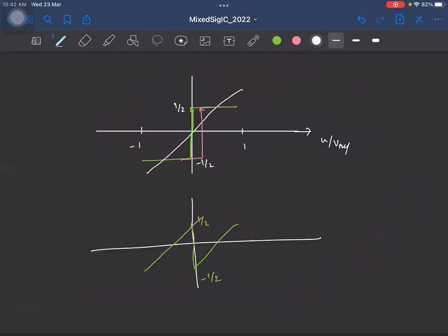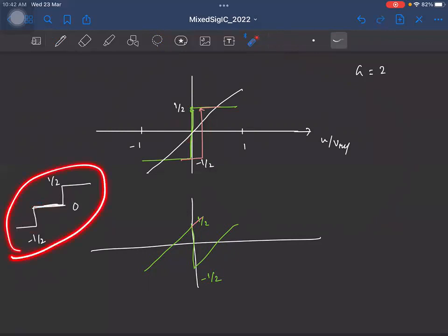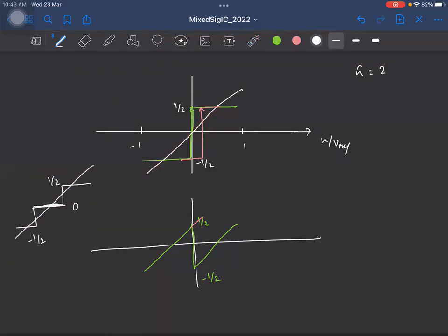So the point is, if I have a gain of 2, having a 2-level quantizer is not going to work. Okay. So what people usually do is they have 3 levels like this. That is, they introduce one more level in this characteristic. So this will again be half and minus half, and this will be 0. Okay, and you add this additional level so that this step characteristic is still a good approximation of this straight line. Let me draw the straight line also.